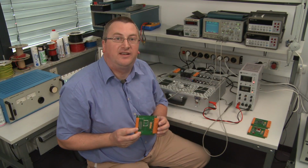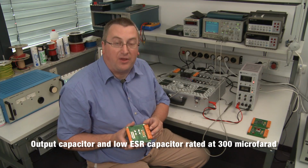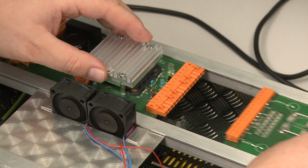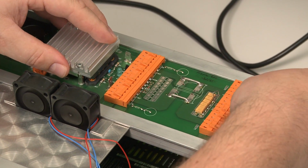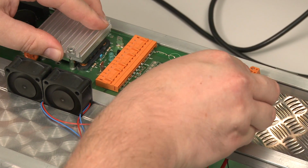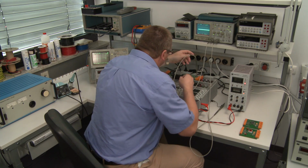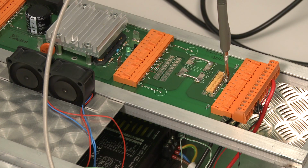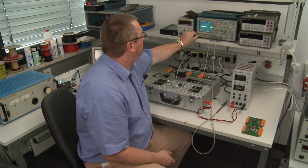The first filter is a simple output capacitor, a low ESR capacitor with about 300 microfarad. I reapply the input voltage and bring in the output load, again the nominal 13.3 amps, and we see the improvement on the output side.